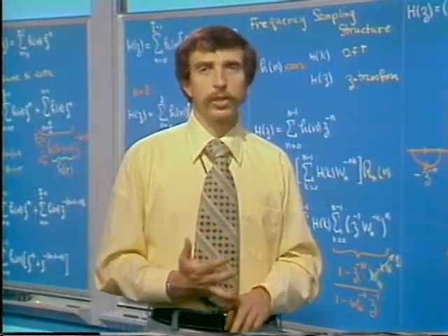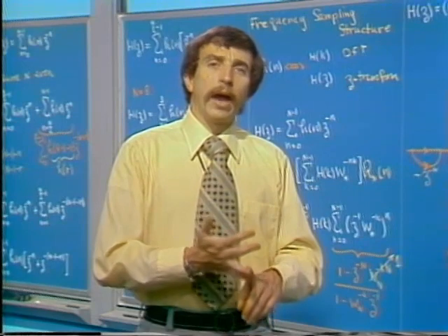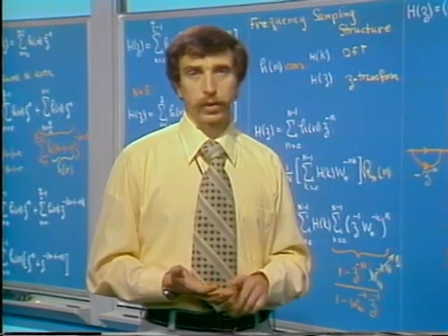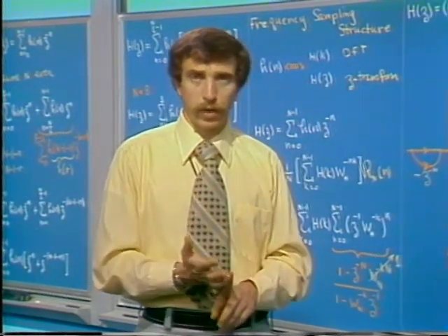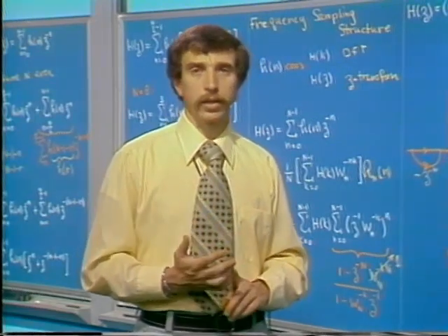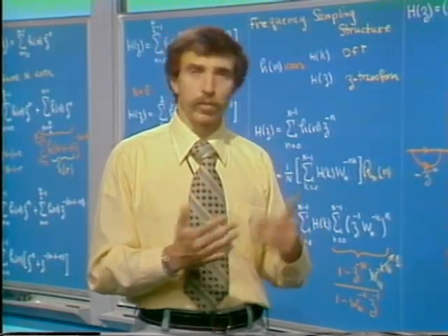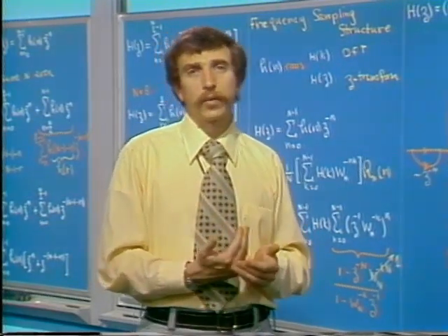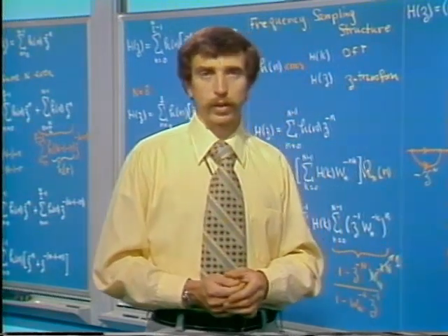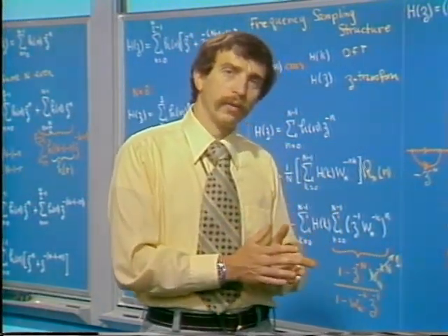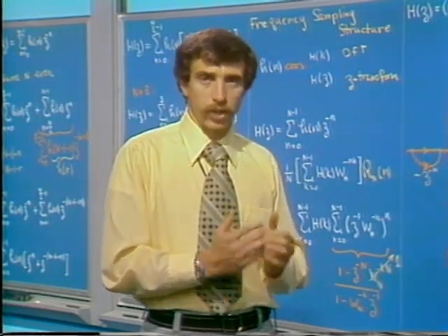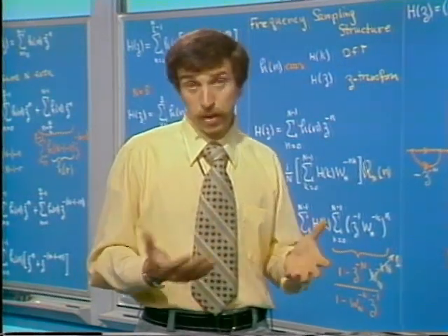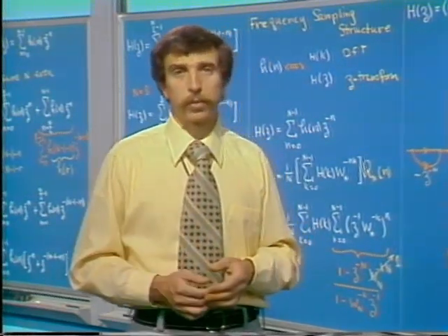One of them has to do with the fact that arithmetic in a digital filter, specifically in a recursive digital filter, has to be done, of course, with finite register length, and it has to be truncated. In other words, multiplications, the result of b bits times b bits, results in 2b bits. If this goes on indefinitely, obviously the register length grows indefinitely. And so the results of arithmetic have to be truncated or rounded. And this generates some noise, essentially, in the filter output.